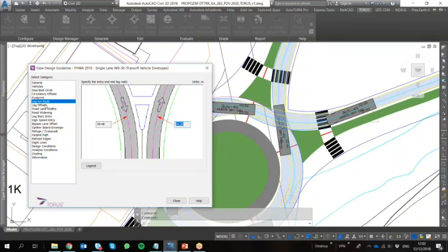So the same goes for the outside. And when talking about the offsets, here are the offsets defined. So to the outside is going to be 2 feet, 60 centimeters. To the inside is going to be 1.5 meters. That results in this median as well. And the values are strange because this is a metric version of the US-based standard, which was originally defined in imperial units. So that's why you see these weird numbers.